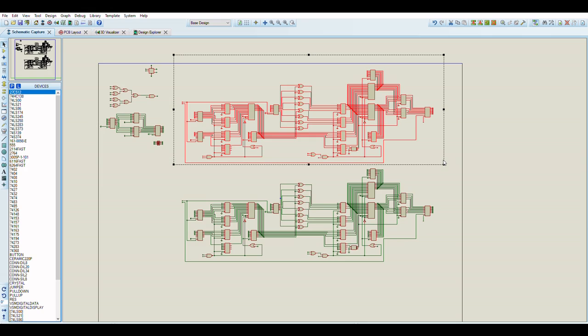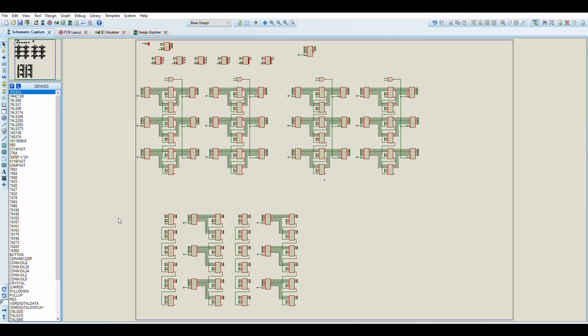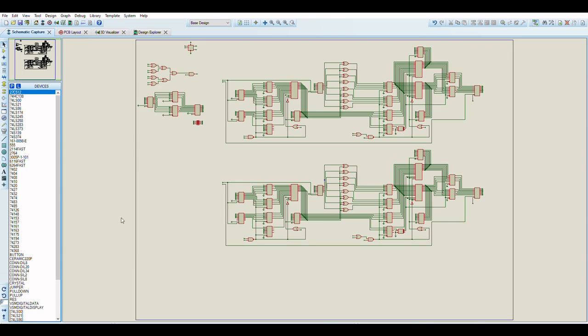This means that with a 6 megahertz clock, it would have given us a maximum of 166 nanoseconds to calculate new virtual screen position coordinates from all of the 6 registers coming in and all of the adding, subtracting and accumulating. It's 2's complement math, so adding is the same as subtracting if you have a 2's complement number, a negative number, right? So adding is the same as subtracting.